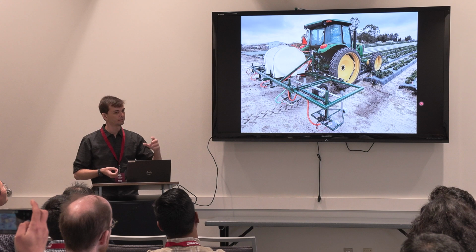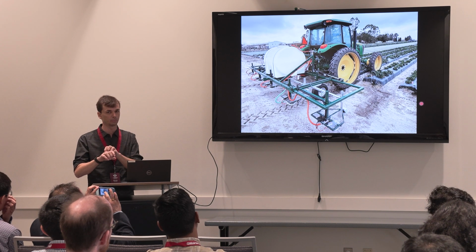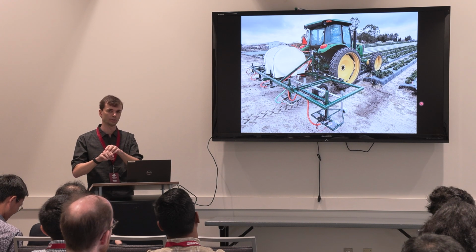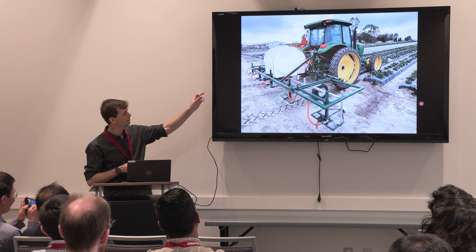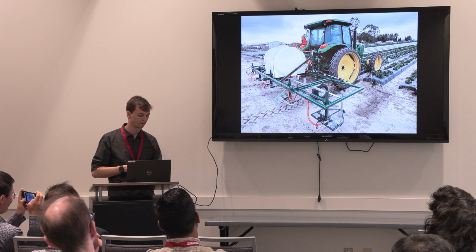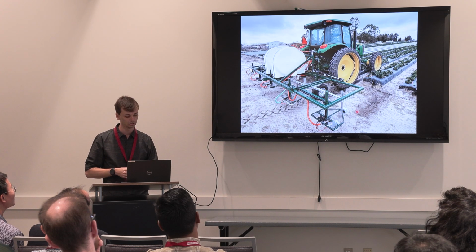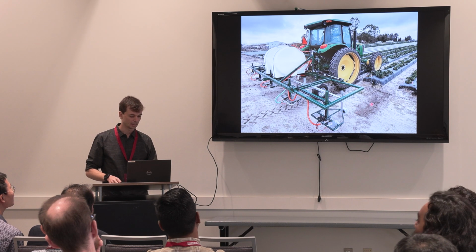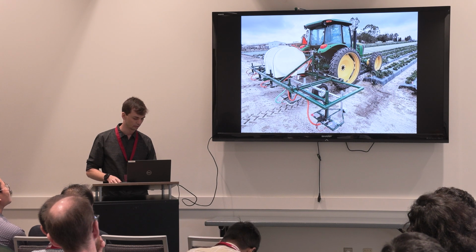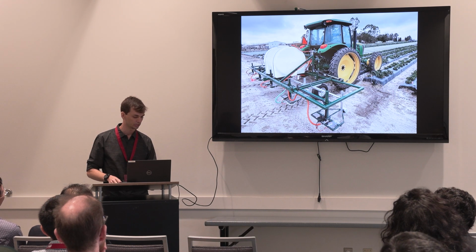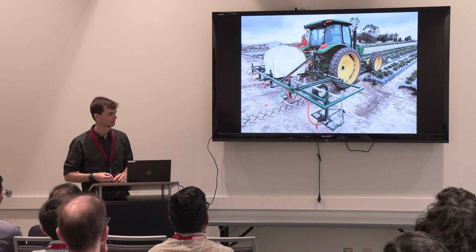Right now we are going to have 5 cameras running at the same time, a single computer and a single YOLO model running multi-thread. So we are going to have 5 cameras and 20 nozzles working at the same time. Basically we have 5 sections, and in each section we have 4 nozzles. So this equipment is for strawberry row middle application. Row middle is the space between the 2 raised beds. So we have 1 camera here and 4 nozzles here. So we have 5 sections, 5 cameras, 1 model, 1 computer, and 20 nozzles running at the same time.